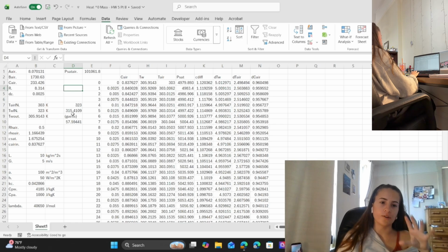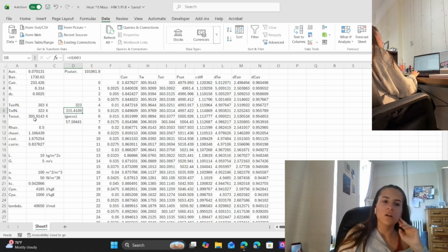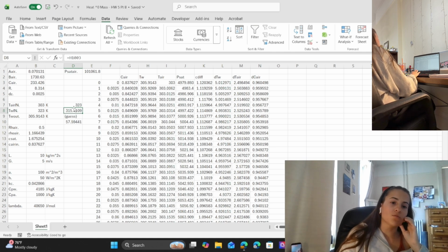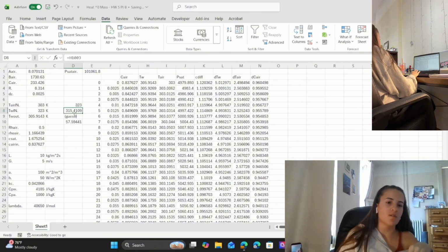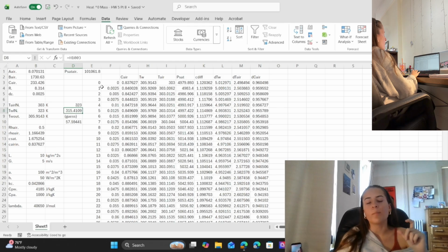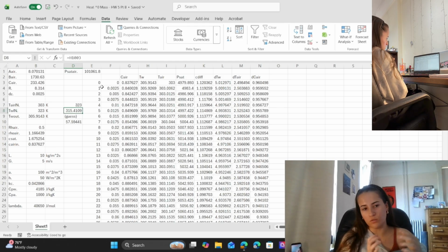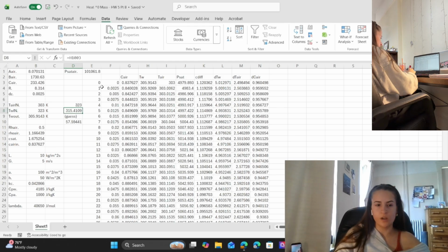It's still colder. So the temperature of the water coming in is colder, and it only gets cooled down by 10 Kelvin. Whereas before, it could be 323 with a taller tower and get cooled to that temperature. So having a shorter length of your tower also changes efficiency to be worse. So we could do Solver again.